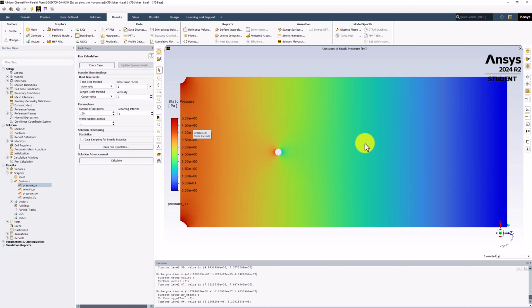We can also see that, away from the cylinder, the pressure looks largely unaffected. We can see the apparent symmetry about the axial z-axis seen in the previous pressure contours, in which the pressure decreases over time but remains constant along a cross-section. Another useful visualization is the wall shear on the boundaries of the model. This is important in understanding the effect of the flow on the bone structure and the forces caused by the velocity gradients in the flow.